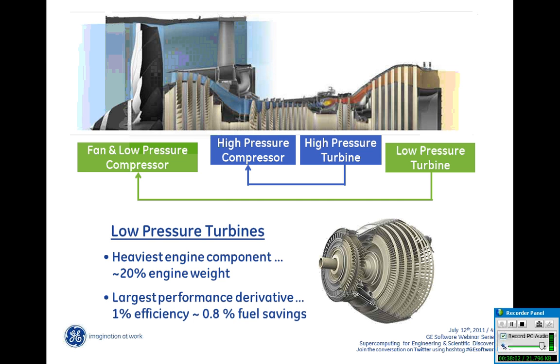boarding an aircraft. The low pressure turbine is so important to our criteria because it's 20% of the engine weight in itself, and we'd like to design that down. And even a small efficiency improvement in there has a substantial fuel savings relative to the overall system.